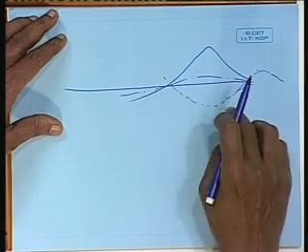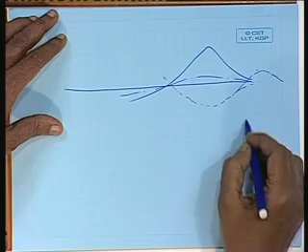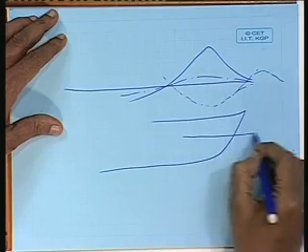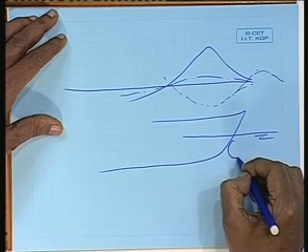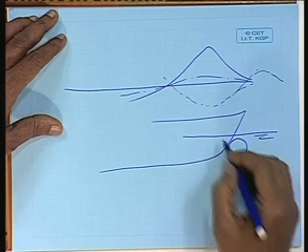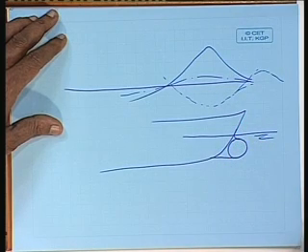And if I can design something which will generate me a wave of this shape. So, this wave may come from a ship like this, moving at this water level, and this may come by putting a sphere here, and so I generate a bulbous bow.